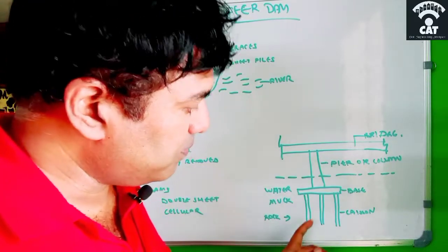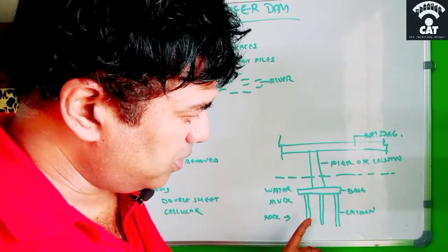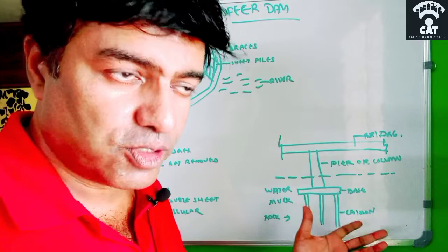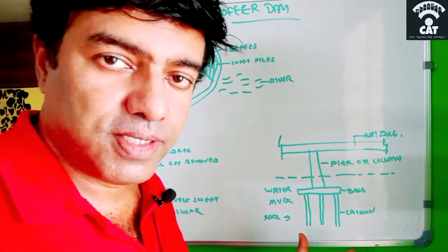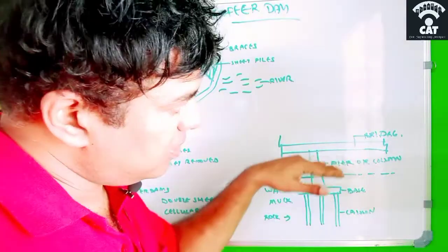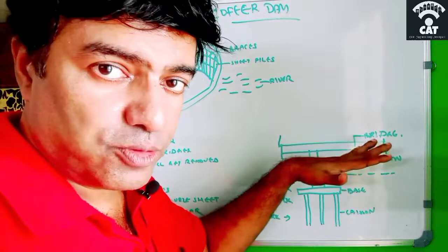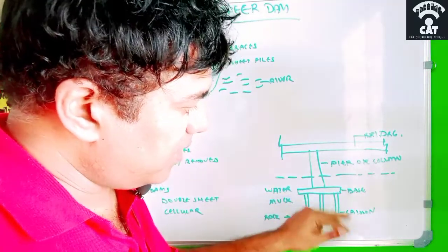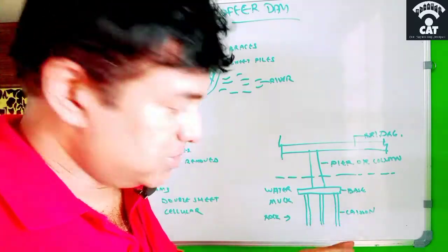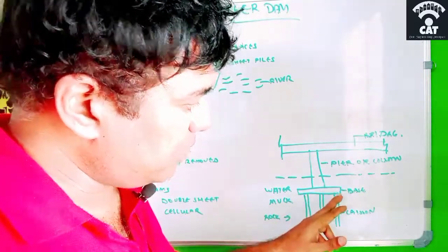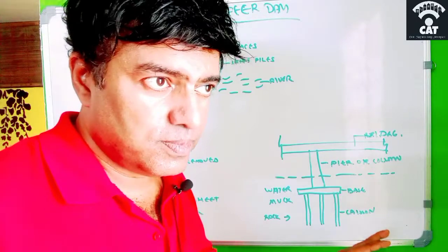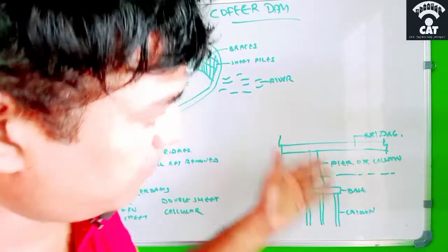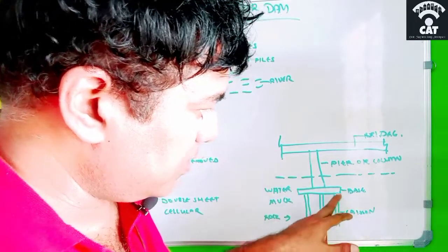They will put one or two caissons according to the load calculation, maybe 2 or 3 or 4, depending upon the design of the structural engineer and the load that the bridge is taking in this area. They drive the caisson, which is going to be a permanent structure, and above that they make a temporary platform, and then they put concrete over it, which will be a base.